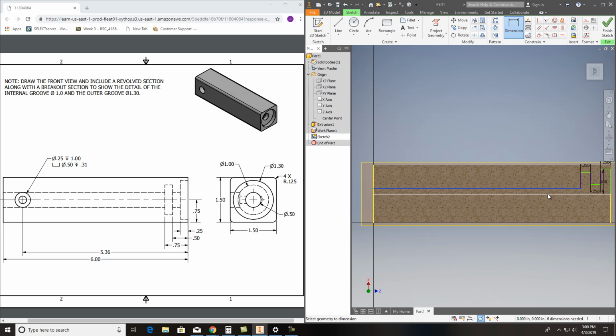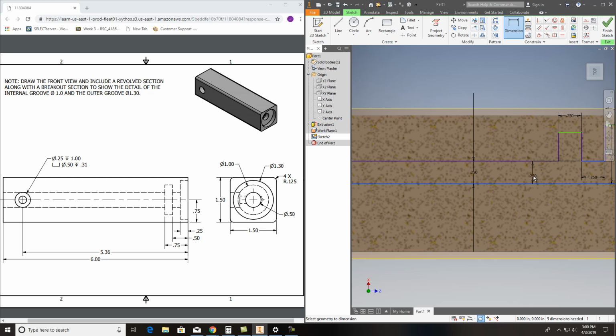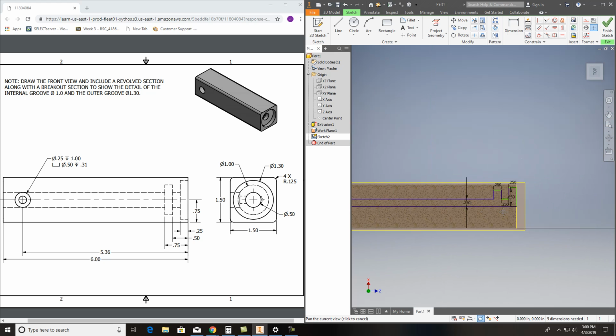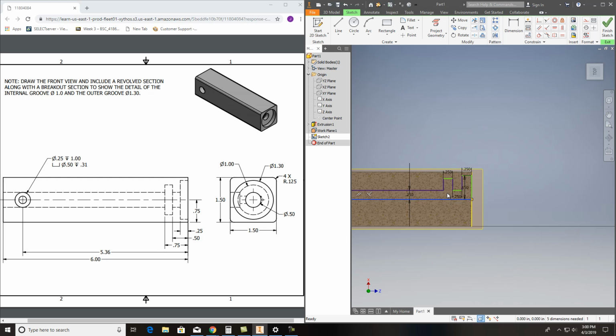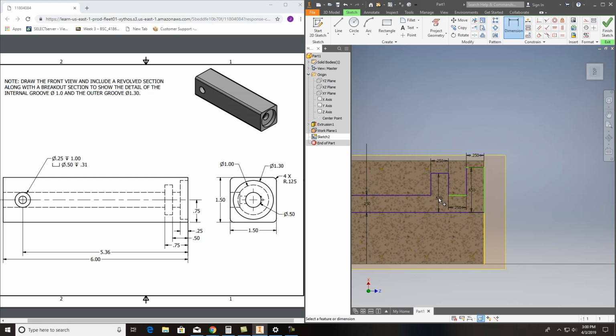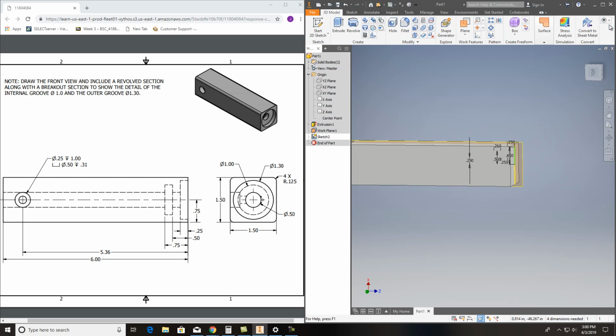This right here should be 1/4 of an inch because we're going to do half of it. This right here should be the same. So it's already set up there. It looks good. Those are already set, so I just got to do this one right here, and dimension from there to there. That should be a 1 inch diameter, so it'd be ½ inch. So that gets all that done, as you can see. All my measurements are in there, so I just finished my sketch.